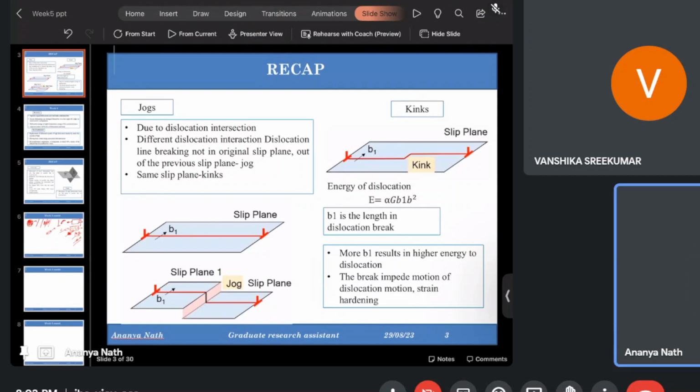Recrystallization also depends upon the prior cold working that you have given to it. Here you are using powder. Yes, you are forcing it to join together, but it will not be considered as cold working because it is powder. Anyhow, it's not possible to give cold working to the powder particles. And also recrystallization depends upon the temperature and time.